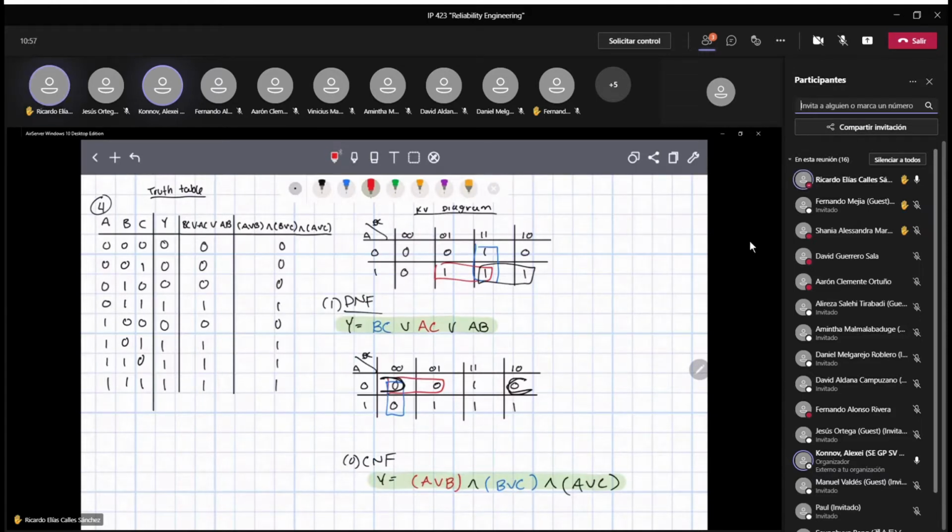So again, here the situation is quite simple. When we are working with KV diagrams, the art to work with appropriate KV diagrams is how to scroll them. So that means how to build the groups. That's all about that. And for that purpose, when the amount of variables is more than 2, as we have here, then the appropriate binary combinations should be written in this way, as you have it right now. So positions have changed from 0, 1 to 1, 1.